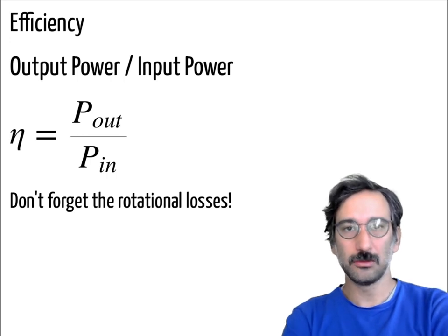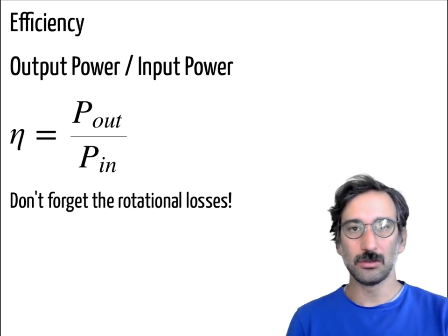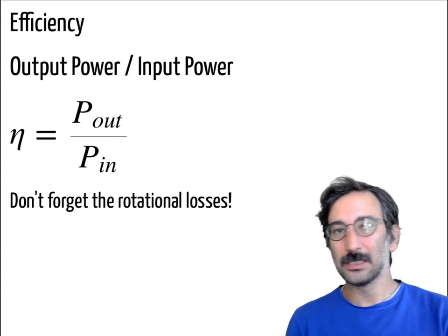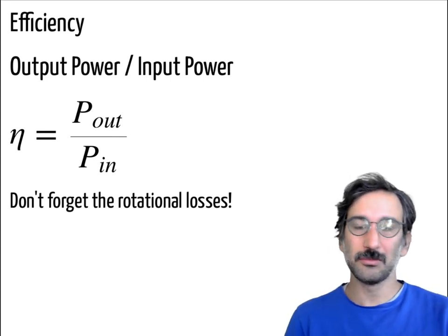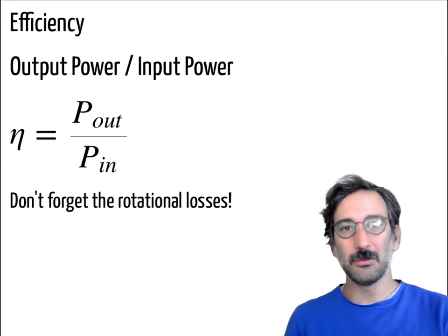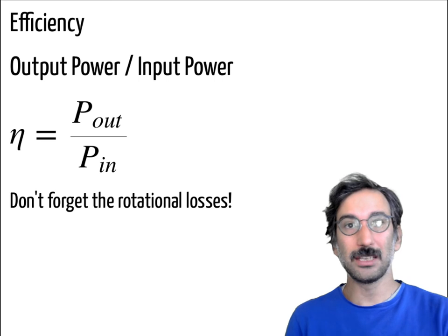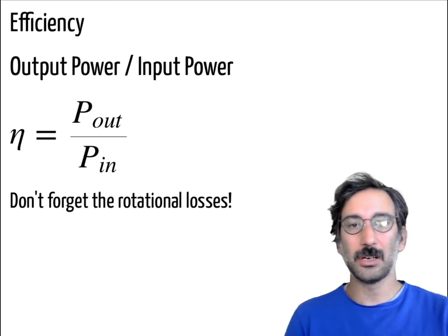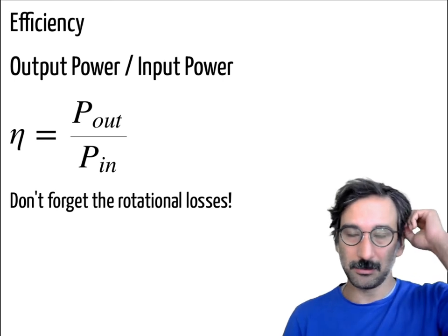So in a normal efficiency calculation, of course you need to put those in. And there is nothing like friction per phase or mechanical losses per phase. So once you get into the mechanical domain, don't forget to multiply your per phase losses or per phase power by 3 to get the total power.